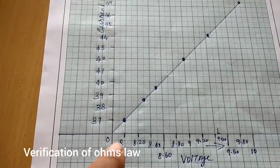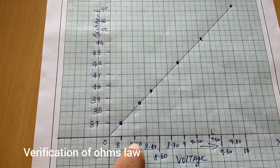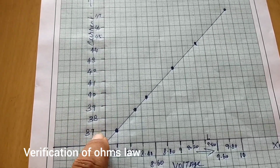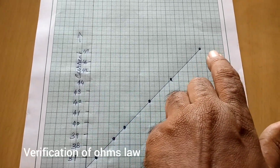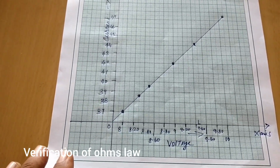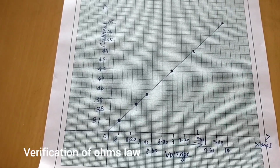Here 1 centimeter is equal to 0.20. Here 1 centimeter is 0.10. Here 1 centimeter equal to 1. So 37, 38. So we get the straight line. We got the straight line. So we have verified Ohm's law with the graph.